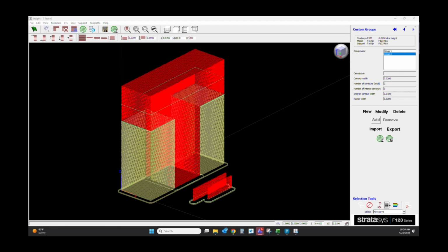If you went to like a 1/2 inch air gap on TPU, that would probably not work. It just wouldn't be able to span. I would probably say a 1/4 inch maximum, and then reduce it by 50% for 3 layers, and then 50% for the next 3, and then 50% for the next 3 until you get to your capping layers.